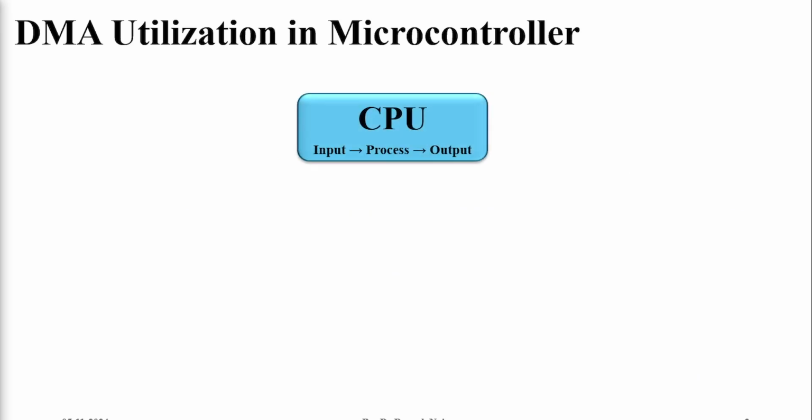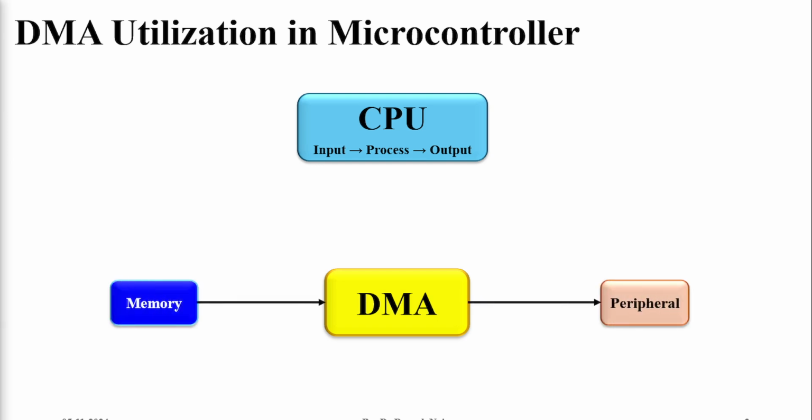Like in the previous video we have discussed, the DMA actually provides a feature with which we can transfer data or large chunks of data between peripheral to peripheral, memory to peripheral, and memory to memory. All this data transfer takes place without the intervention of the CPU. Therefore, the CPU can be used for some more important task when the data transfer is taking place. In this example, we are going to take some data from the memory and pass it to the USART and get it displayed in the serial monitor.